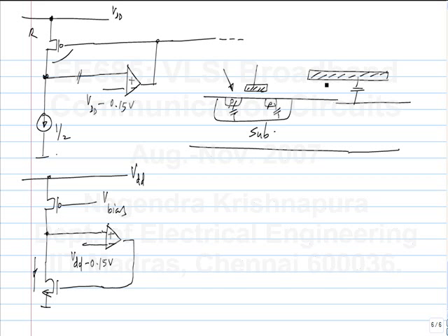Now, this very much depends on the resistivity of the polysilicon. If the resistivity of the material is very low, then you need a lot of material to make the same value of resistance. In that case, the size of this is much more than the size of this, and that may offset the advantage of distance. But if you do have high resistivity material, then you can make a compact resistor which has a small parasitic, okay.